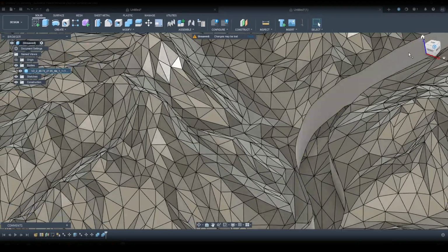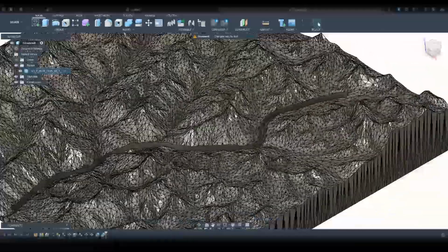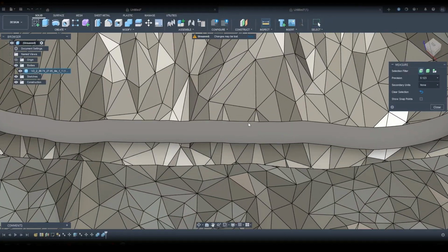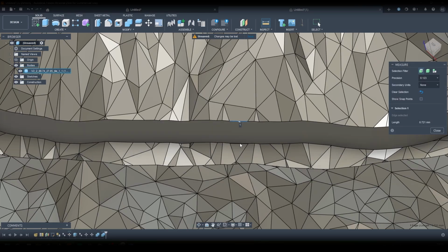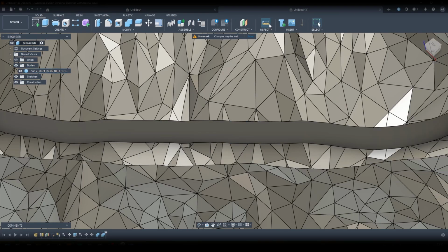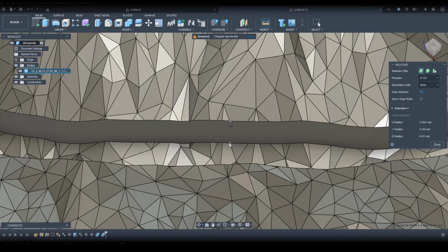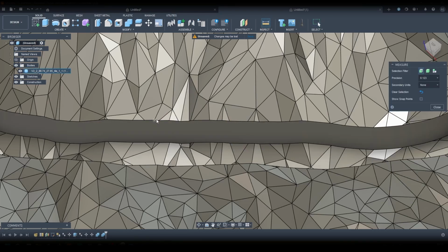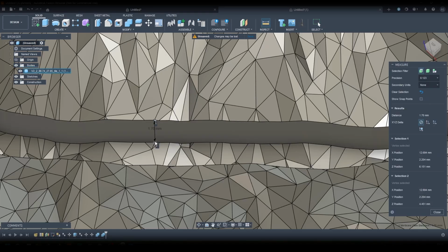There are probably other ways of doing it. I could follow the curve using other tools, but I wasn't able to follow the peaks only because there were lots of different faces and then lots of different planes. And if we check, so if we get 2 points together using the inspect measure tool, you can see it's 1.7 millimeters across various points.